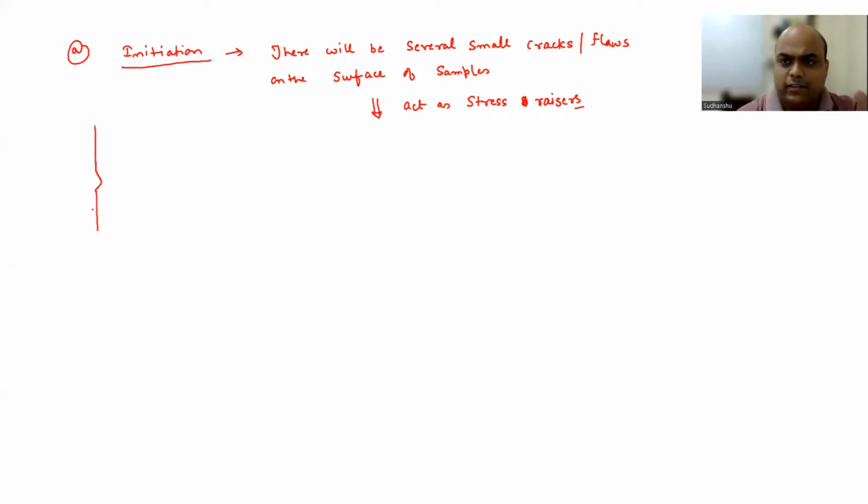In this case, it's a notch. Suppose it's a notch. Even a crack will be something like this, or scratches, right? Now, if you see this, there will be stress concentration in front of this surface defect.